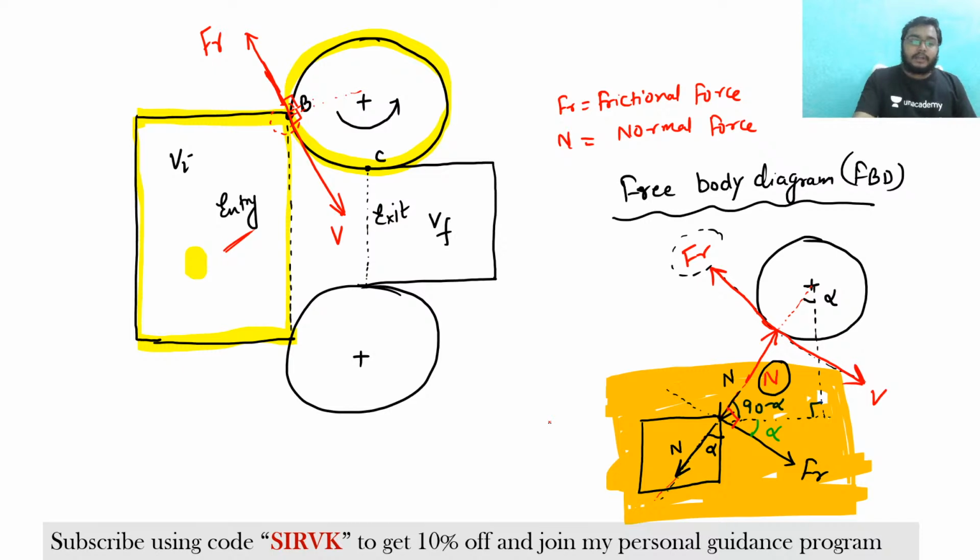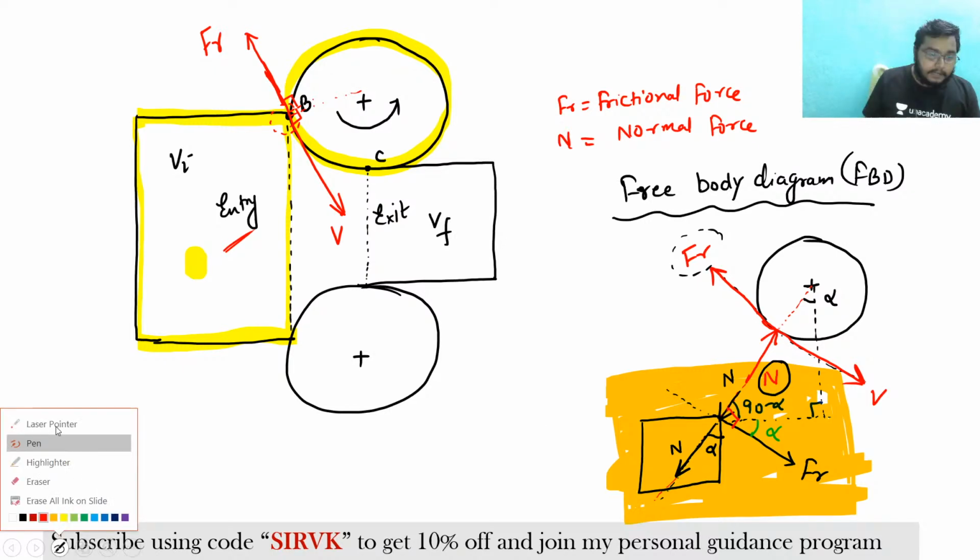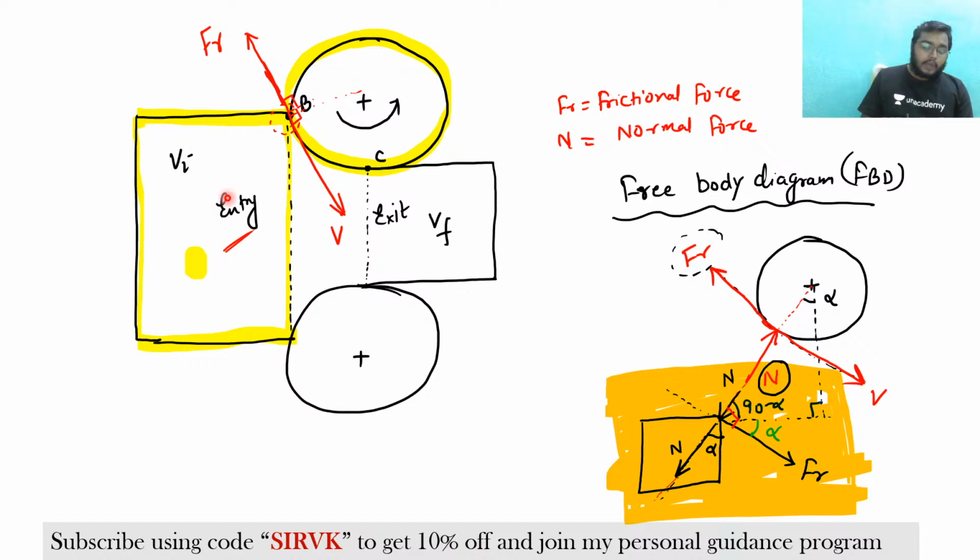So see here, what is the meaning of self entry? Understand that this is the workpiece that I am feeding here. So I am giving the workpiece from this entry end. So what we can understand, from this B point to the neutral axis, my frictional force is acting, and there should be a condition of self entry.